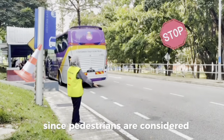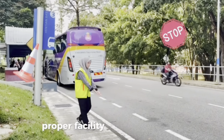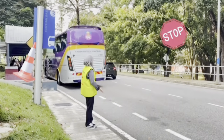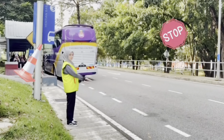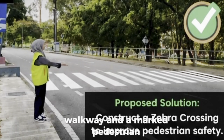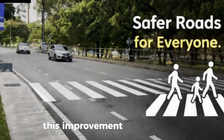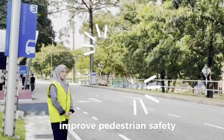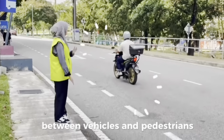Since pedestrians are considered vulnerable road users, proper facilities should be provided to ensure their safety. Therefore, we propose the construction of a pedestrian walkway and a marked pedestrian crossing near the bus stop. This improvement would provide safer access to public transport, improve pedestrian safety, and reduce potential conflict between vehicles and pedestrians.